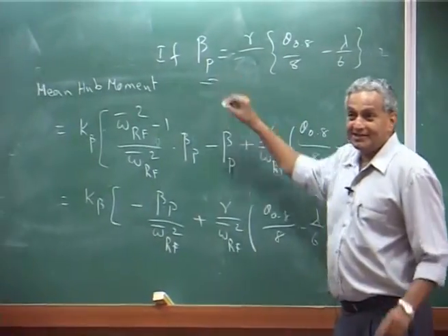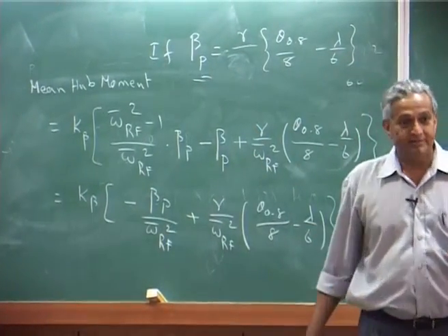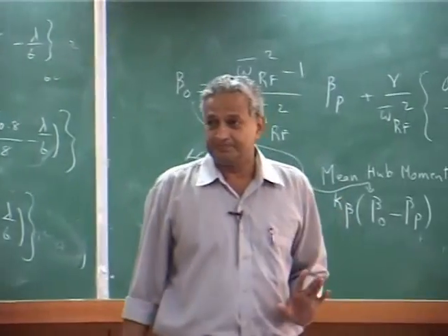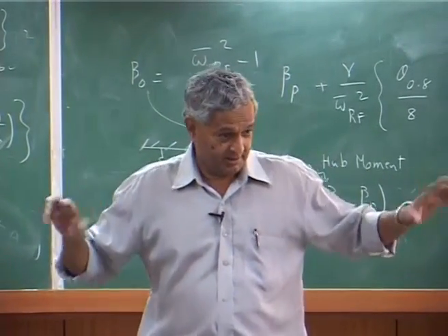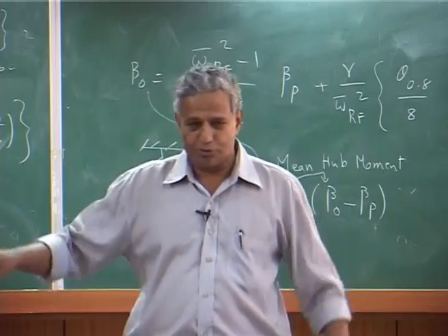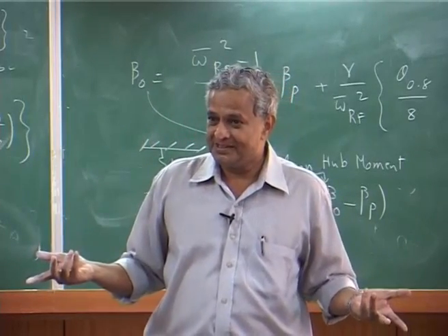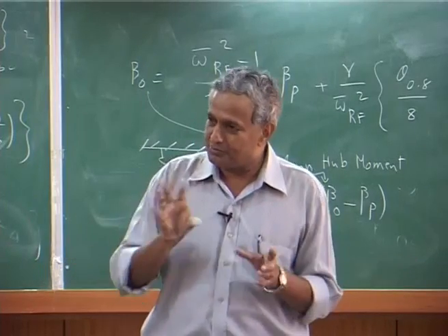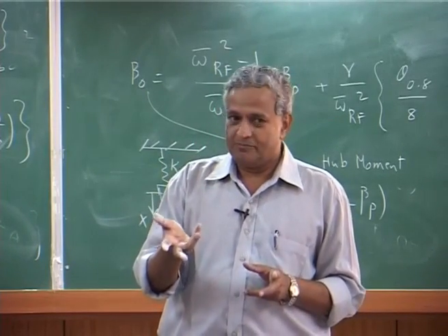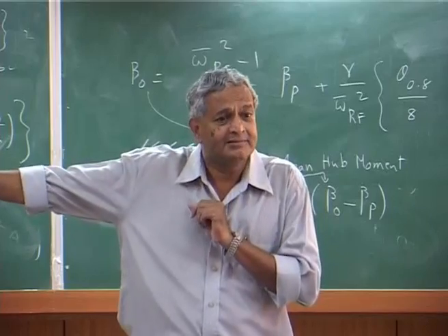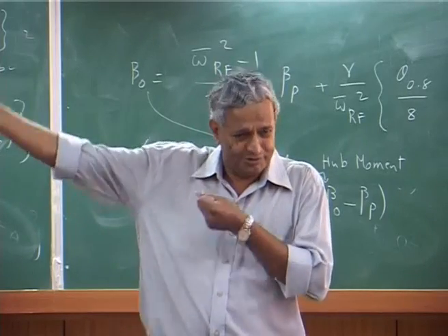Now, you know why rotor blades are given slight precone. Only when you have a root moment, if it is a pin, there is no, that moment is 0. Centrally hinged, no problem, but the moment you put a spring, it is like a cantilever first mode.